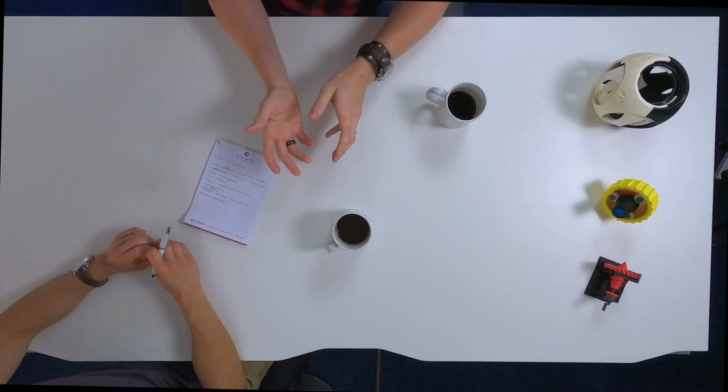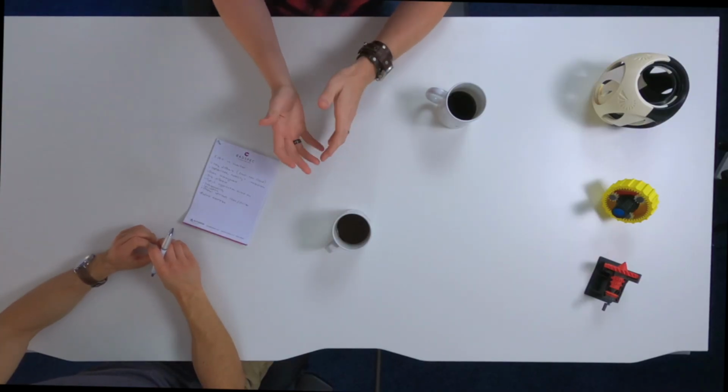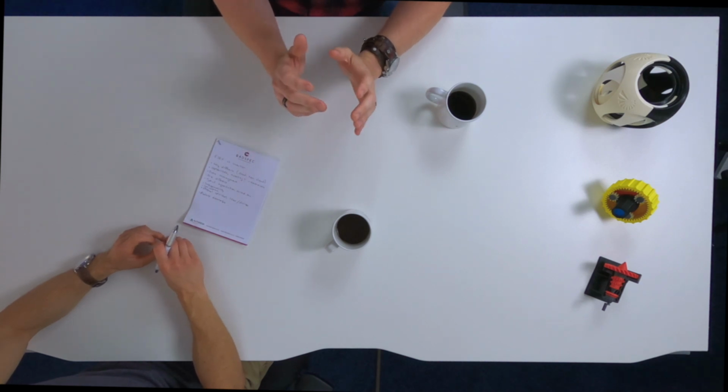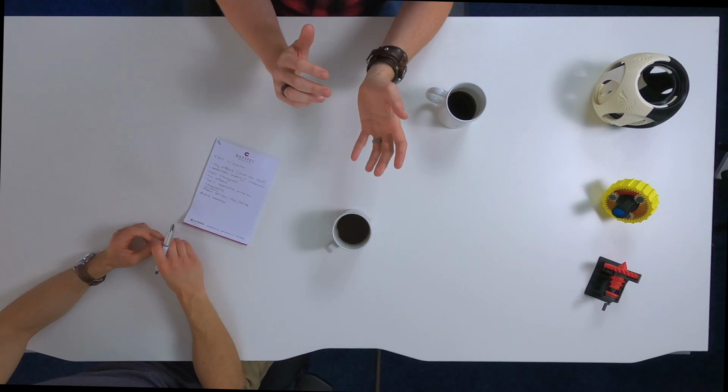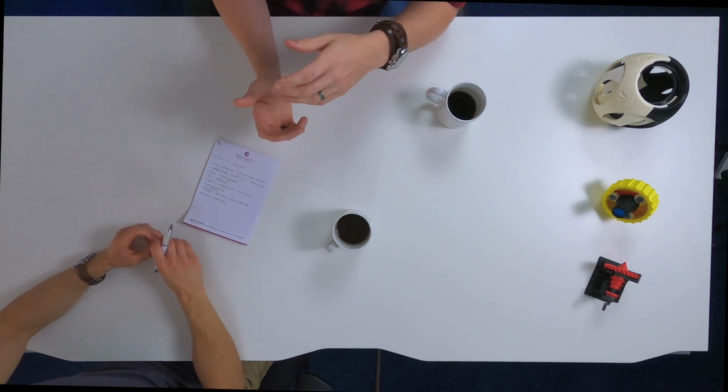But when I'm looking at Inventor, I'm looking at a tool that's been around a long time. It's able to do large assemblies. It requires a bit more processing power. Whereas Fusion 360 is a lot newer. It has a lot of functionality that Inventor has as well. However, when I'm looking at things like large assemblies or things where using a design accelerator in Inventor would make the design work a lot simpler and faster, Fusion 360 isn't quite as strong as Inventor in those subjects. However, Fusion 360 does have some aces up its own sleeves.